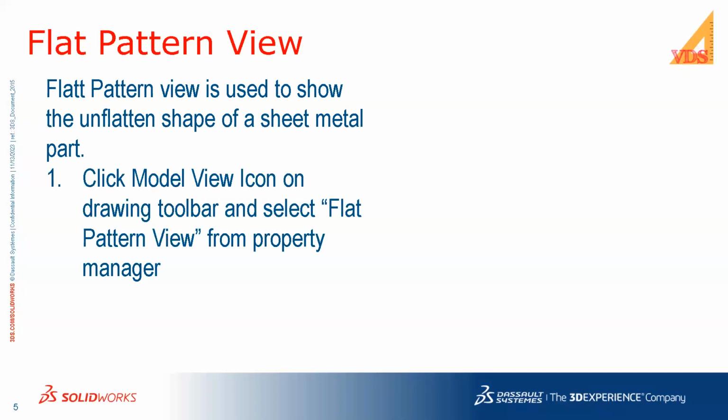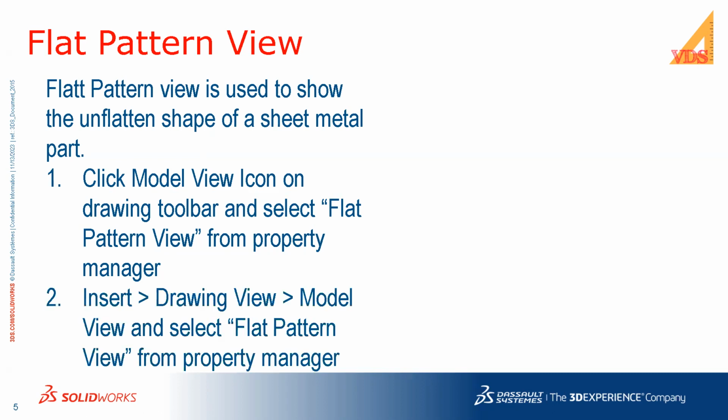Now, how we can create a flat pattern view in a drawing: when we bring a sheet metal component into drawing mode, SOLIDWORKS gives us the option of creating a flat pattern view in the same property manager, or we can also do it when we insert the model view. From there also we can select the flat pattern view in the property manager. There is no direct tool to insert a flat pattern view directly into the drawing.